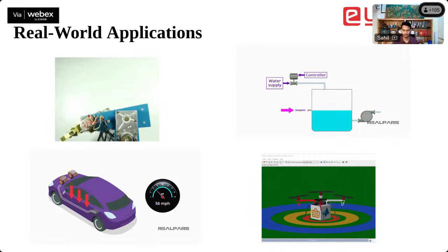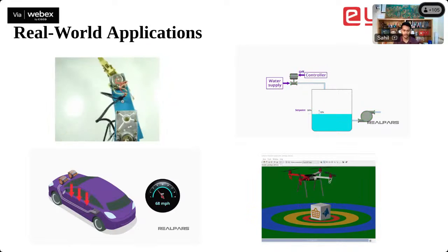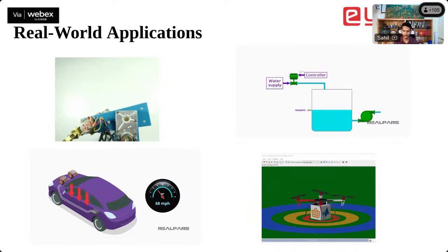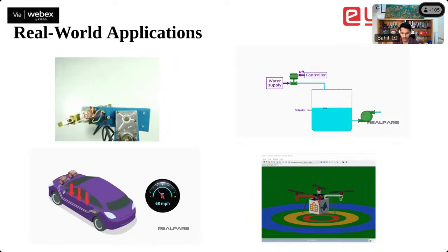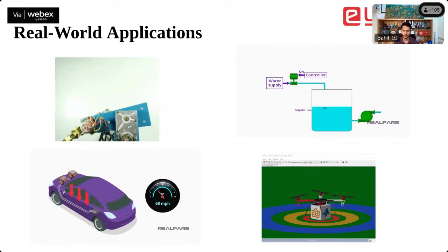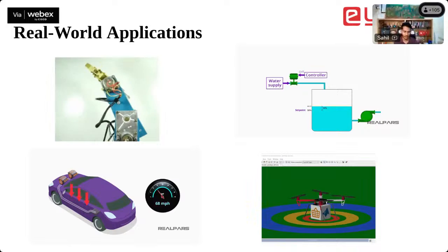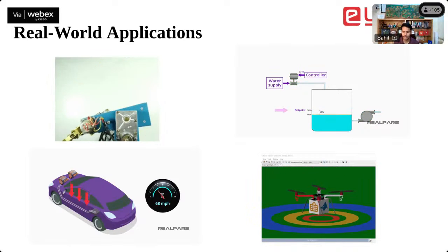So now, why does the derivative term need filtering? The D in PID stands for derivative. It predicts how fast the error is changing. This helps smooth the response and prevents overshoot. But here's the catch: real sensors like gyroscopes or encoders often give noisy readings.